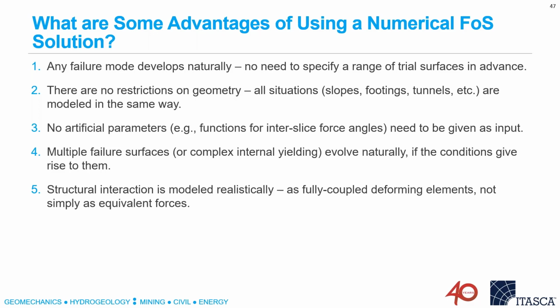arises. The numerical methods don't have any artificial parameters such as interslice force angles that have to be provided. And as I said, we can get these multiple internal surfaces that evolve naturally when the conditions are right. But I will say in my work, this particular feature pops up more than we might think.